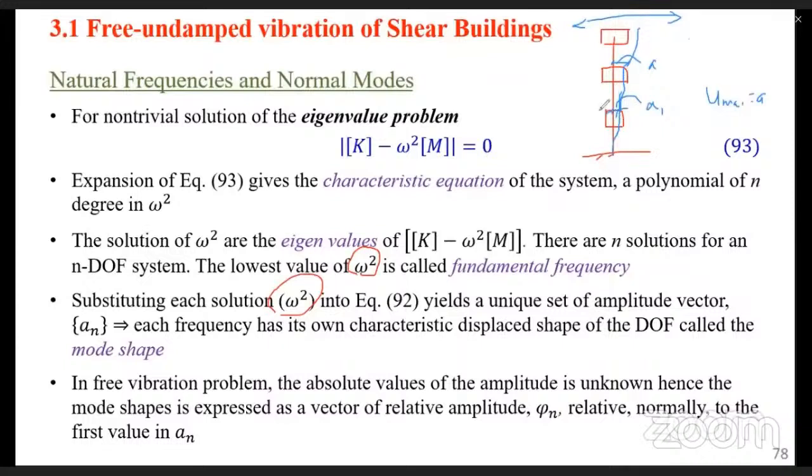So the second mode, let's go back. This could be in this direction, and it is given by calculation of these A's. If you calculate the value of A and get a negative, and you started with this direction as positive, then the negative direction is on this side. If A1 is negative, the mode shape goes to this side. If A2 is positive, it goes like this, and if A3 is positive, then it's like this.